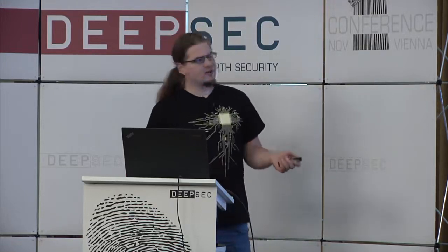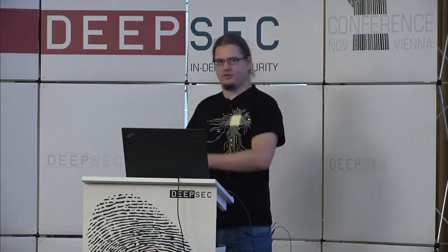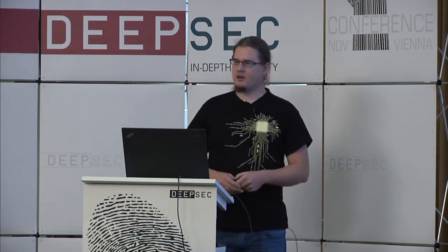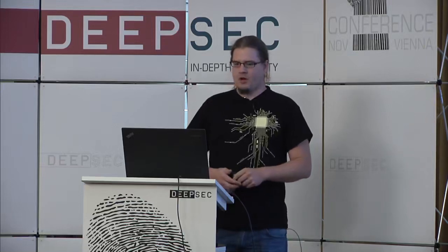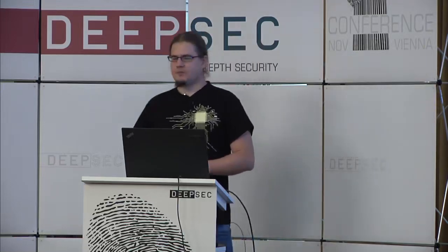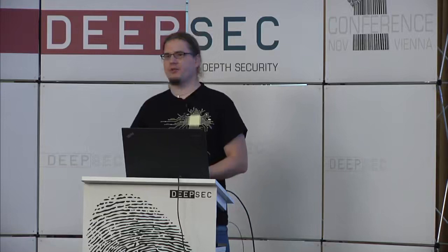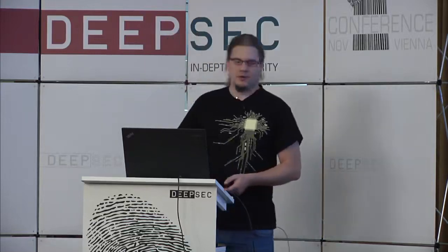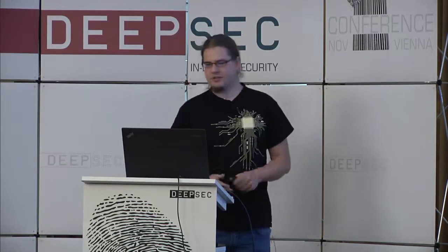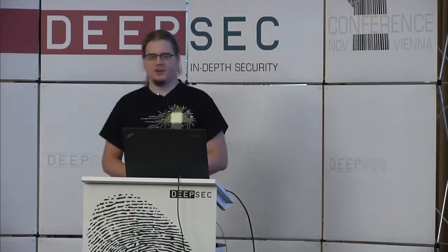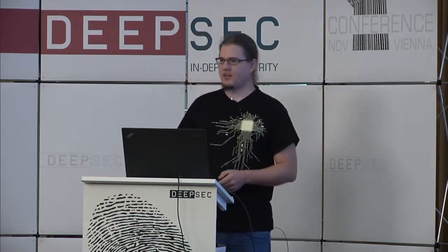As you can see down here, there's a flag that you can set when the device is going into production, for the final release to the customer: you can set the readout protection flag and you're no longer able to read out the firmware via SPI. Another interesting thing is the non-volatile memory on that chip. You can store configuration data, maybe cryptographic key material on that. We will talk about this later. You can access the normal endurance non-volatile data from SPI, but the extended endurance section is not accessible via SPI.